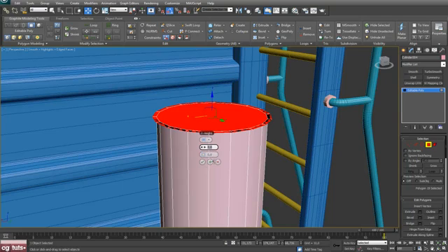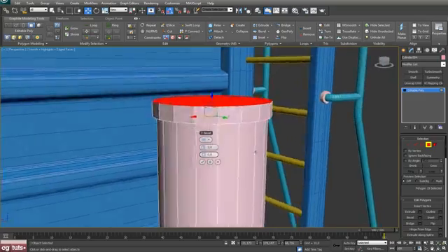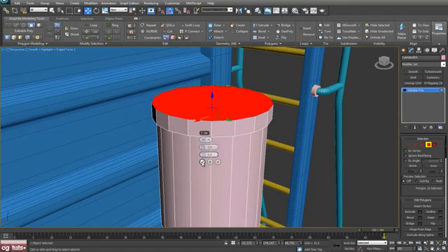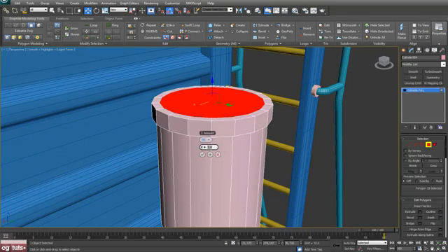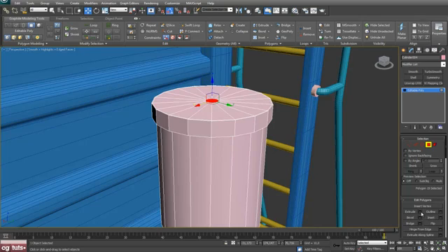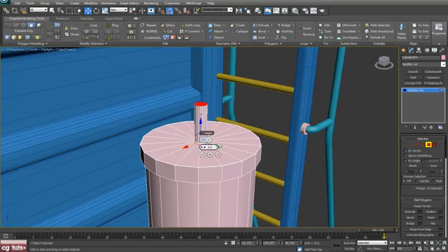And let's make height now 2, that will be okay. And now hit okay, hit inset 0.1 and hit apply and continue, and let's make 6, maybe 6.5. Okay, and now hit extrude 2.5, hit OK, and now again bevel, height 0, and let's try with outline 2, apply and continue, and now make height 5, maybe 8.